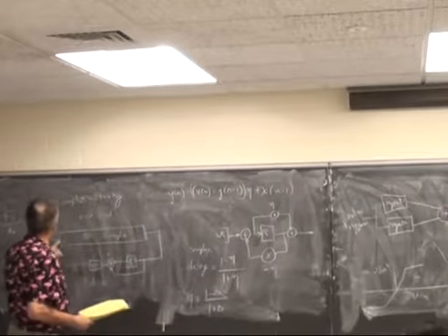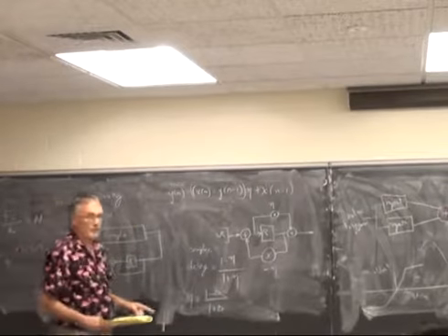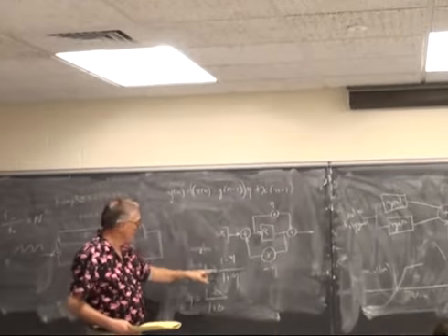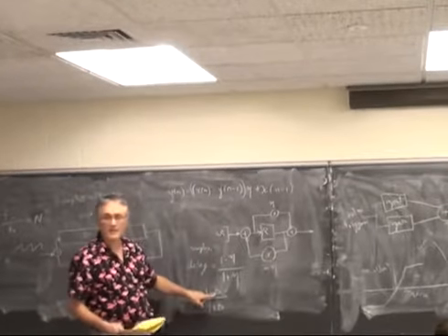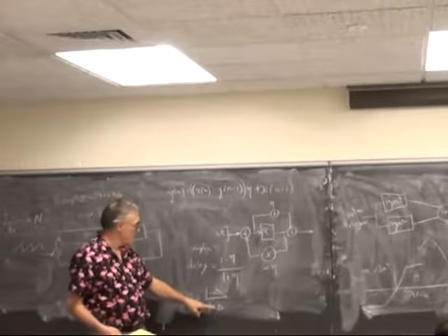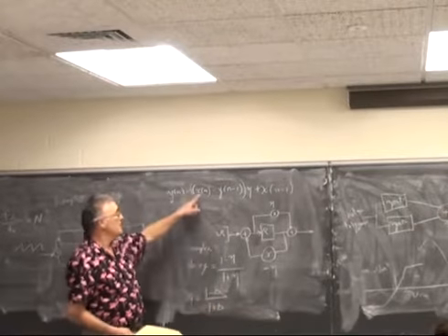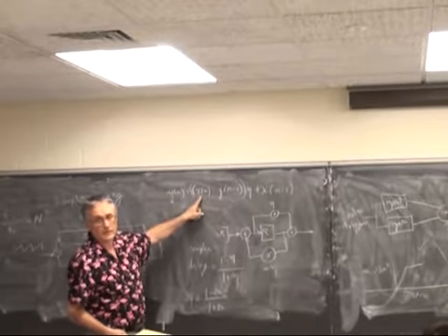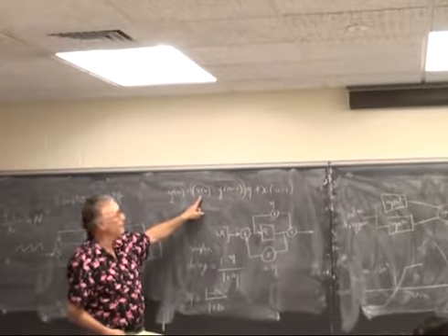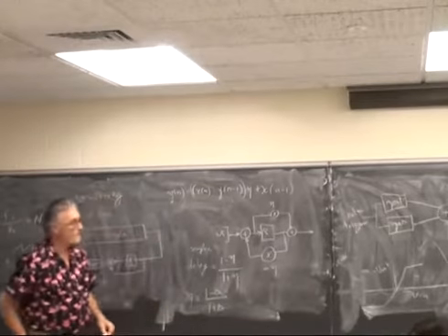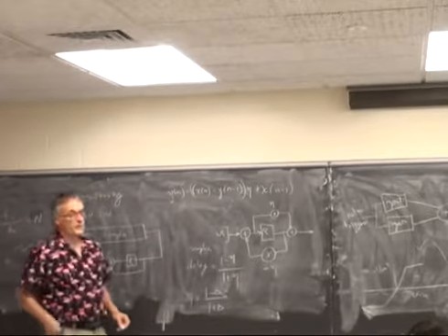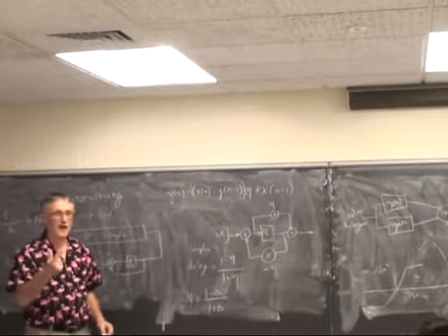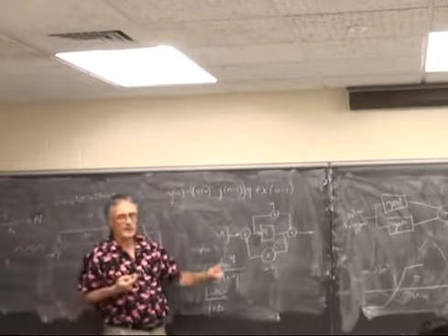So in the case of where I needed 30.58, I would make my shift register 30 stages long. I would plug in 0.58 here for the delay, calculate the eta, and that would design the all-pass filter necessary to phase shift half of a sample, 0.58 of a sample. So you coarse tune with the number of stages in the shift register, and you fine tune by changing eta.